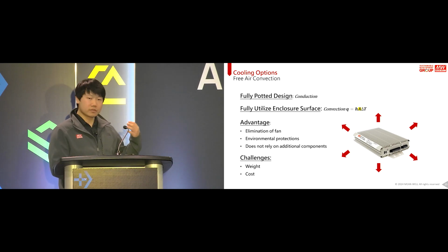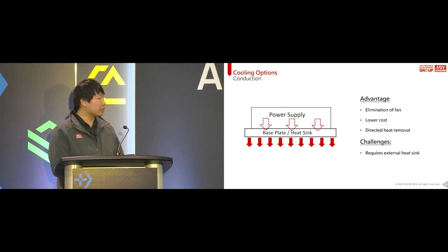And since we are using potting compounds to get rid of the heat and to provide the environmental protection, sometimes these power supplies may also weigh 3-4 times more than another, like a forced air cooling power supply in the same power range. And next is the conduction cooling.